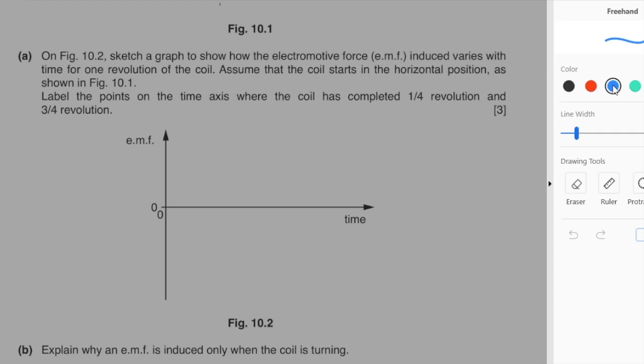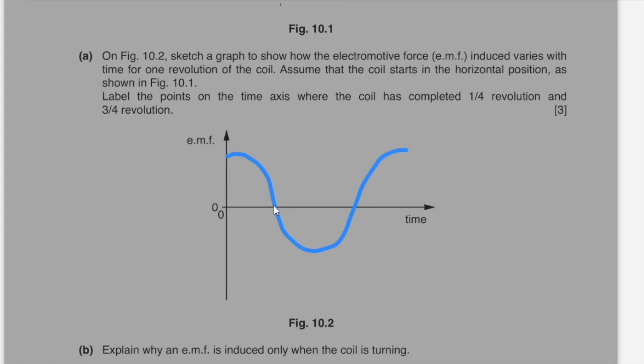So we have one entire cycle over here. This is when the coil is horizontal, and then it decreases when the coil gets vertical over here. I'm going to be marking this as the quarter cycle because it forms the 90-degree angle, becomes vertical, and cuts no magnetic field lines. Once again, this is when it completes the half of the cycle and reaches 180 degrees.